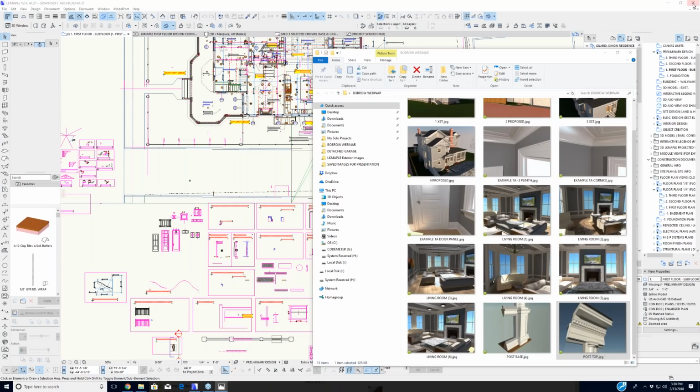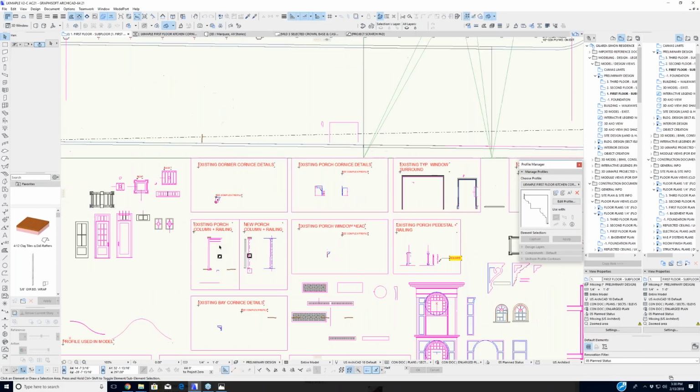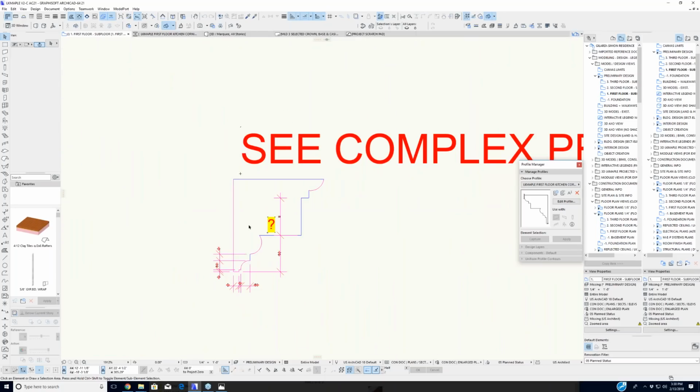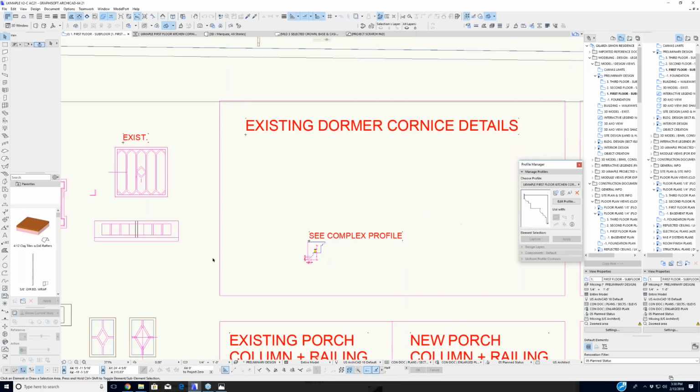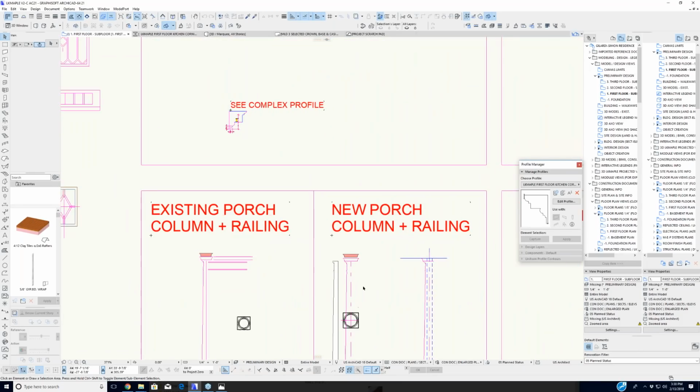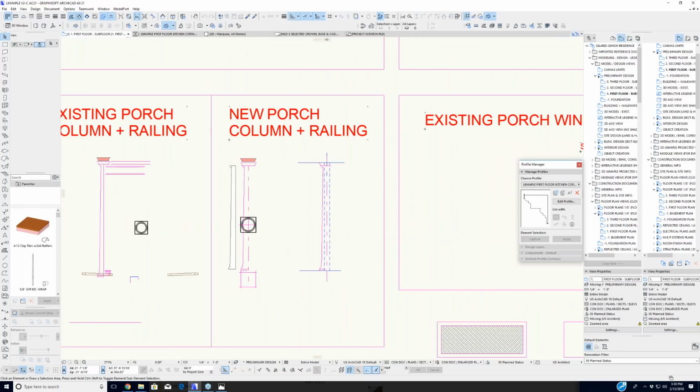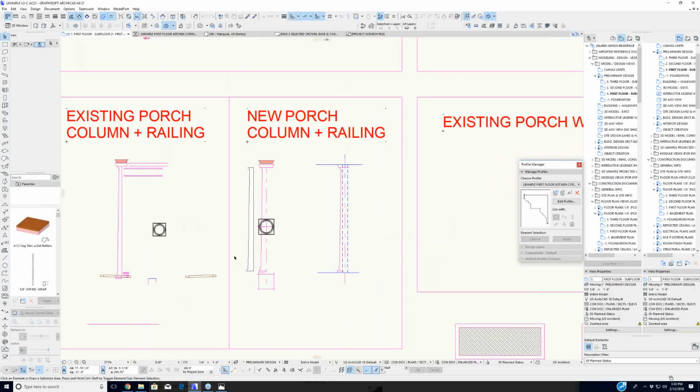Then, when I'm back on the plan, I can either print that out 1-to-1, in other words, full scale, and plot it. So what they're going to do in the field is print that out, take my print, which is 1-to-1. It barely fits on a 2x3 foot sheet. If it doesn't, I'll send it out on a 3x4. They'll tape it to a sheet of Luan, and that becomes their template. They'll cut out a sheet of Luan, which is 1/4 inch plywood, and cut that.